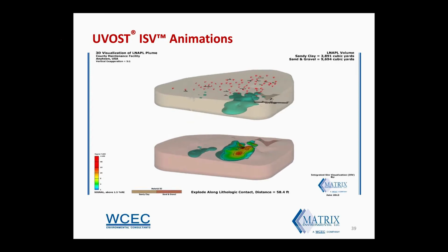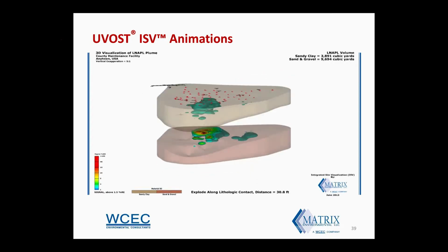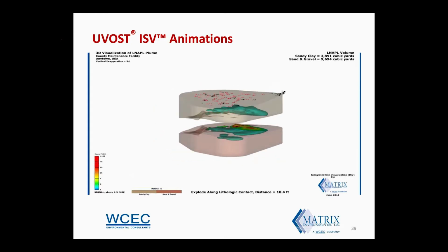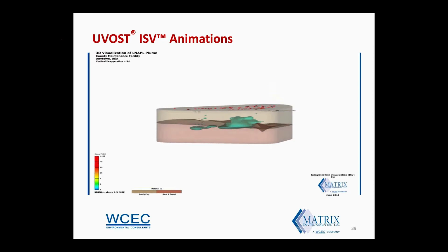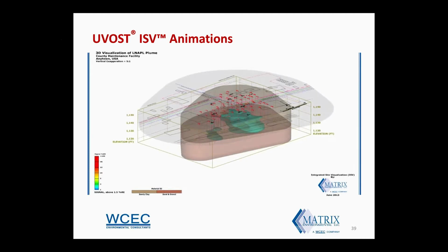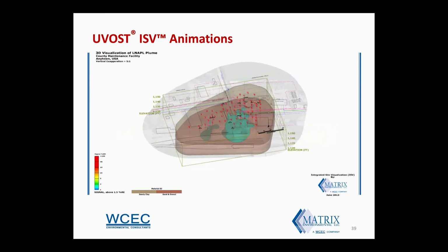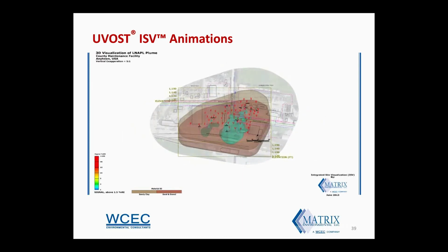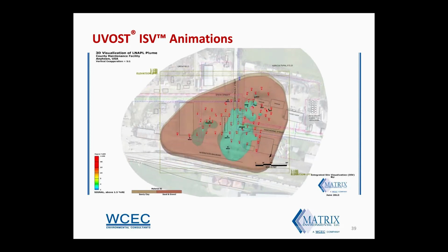We can actually use this kind of data to calculate an estimated LNAPL contaminated soil volume in each geologic layer and in total for planning purposes for, say, a remedial excavation. And then we usually return these back to a map view showing all the relevant features.